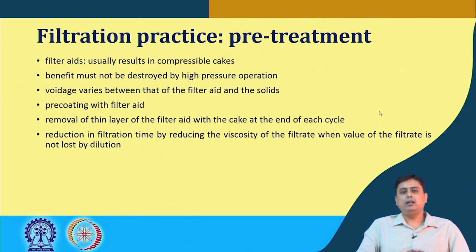This can be prevented by operating the washing at a lower pressure drop, so that this change in porosity or the expansion of the bed does not happen. So, these are the practices in filtration, pre and post process.